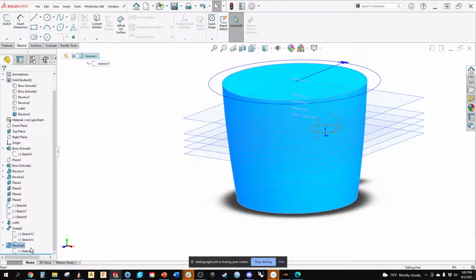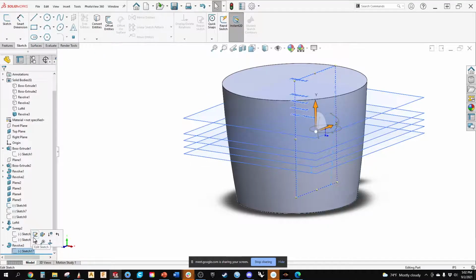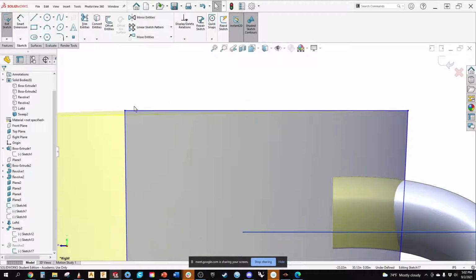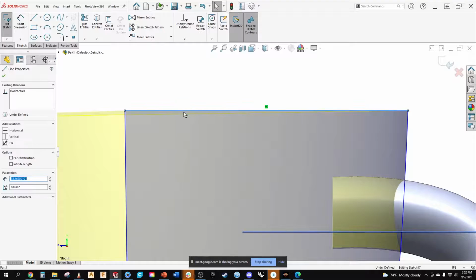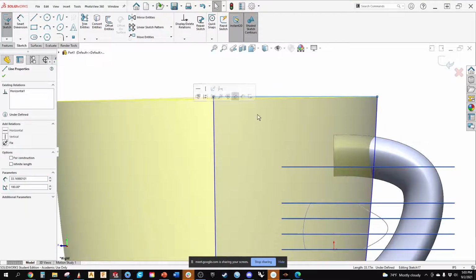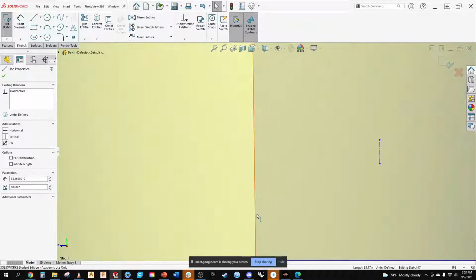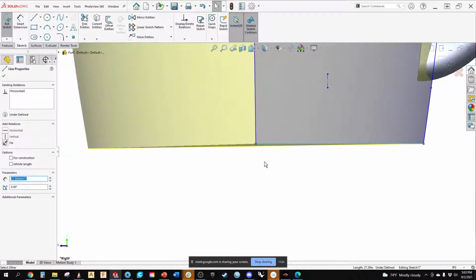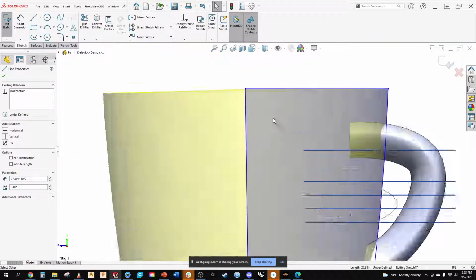then I need to go back in, look at my profile sketch, and go, oh, so it's revolved, but this isn't planar. So let me make it 100% horizontal. We'll make this horizontal too, which it is.